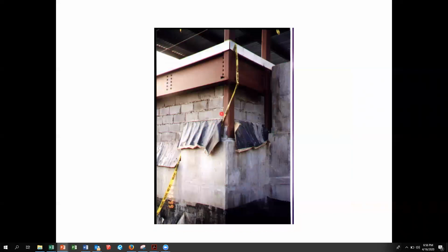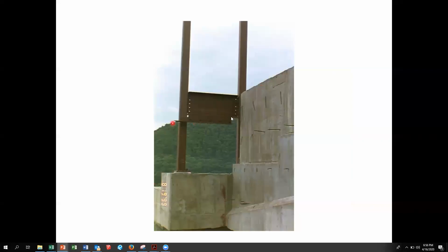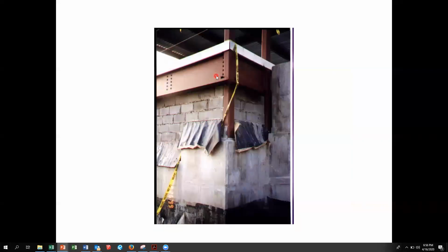And there's that same angle that you just saw right there. So this angle right here is that angle right there. And then there's another beam that wraps around, and it has an angle attached to it. So the brick sits on the concrete right here, comes up underneath this. This is called that soft joint that I was telling you about, so that the brick can expand. And then a new course of brick starts on the steel angle.